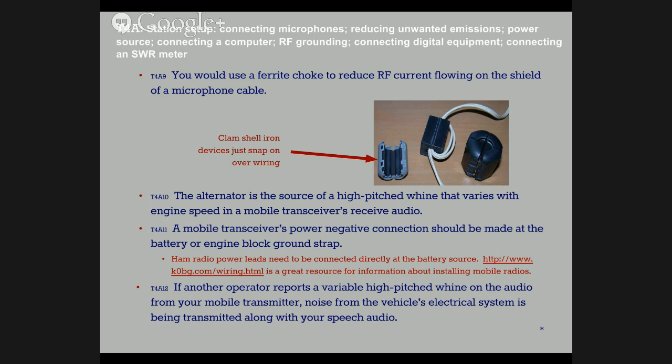It's generally a good idea to always connect transceiver power directly to a battery. This website here, k0bg.com, provides an excellent guide for installing mobile transceivers. It was an invaluable resource when I was setting mine up. And it'll talk about the importance of fusing and dealing with alternator and ECU whine.